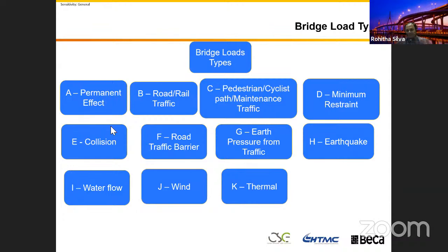After the flood, everything is finished, but the scour around your pier is still there. That is the aftermath of the flood. So you have a 1 in 2000 year scour, but you don't have a flood load. That scour means you have an unsupported length of your pile, which makes a massive flexibility in your bridge, and whether it can take the braking load.